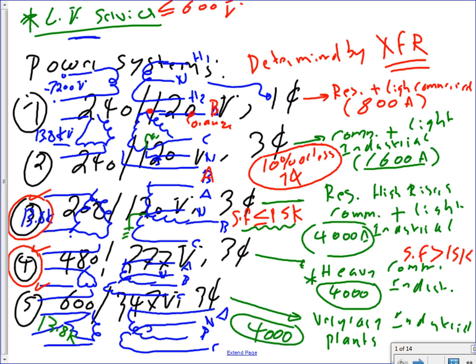And the voltage that you get is 120/240. We designed a project, an apartment building. Last project was what? 120/240. It started with this power system, which is a 120/240 transformer. Can you see the primary voltage, the pole-mounted transformer that Xcel can give you? The primary is typically 7,200 volt to ground. Any questions about system number one?